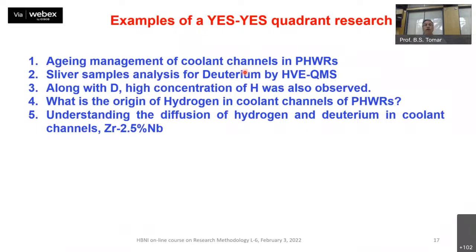At 250 degree, accordingly, every 50 degree it goes up, the deuterium content doubles. So they need to measure the deuterium content periodically so that we don't exceed that concentration, which will lead to blister formation. And that is done.